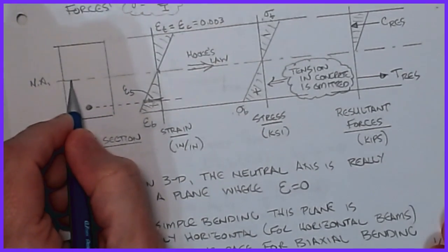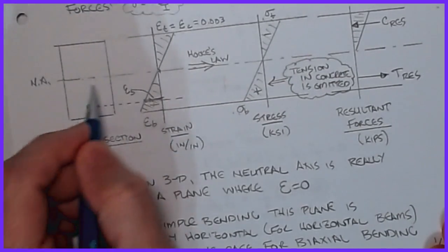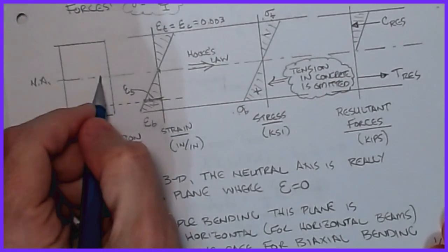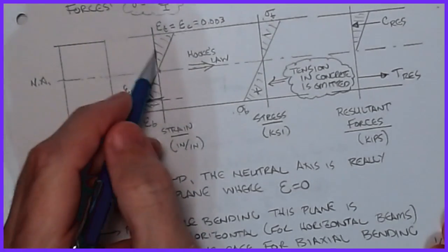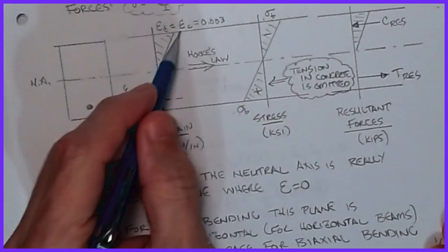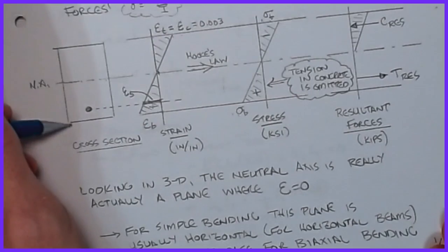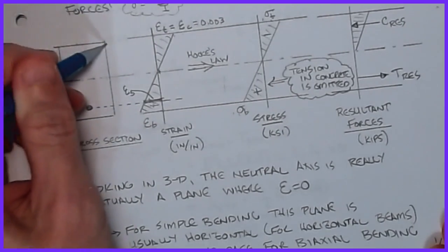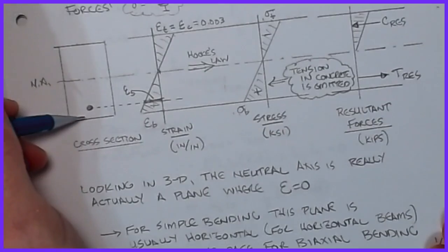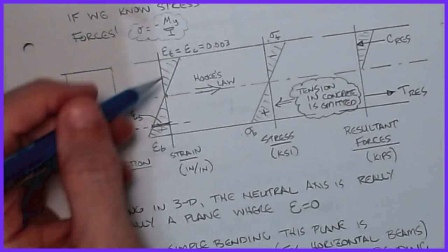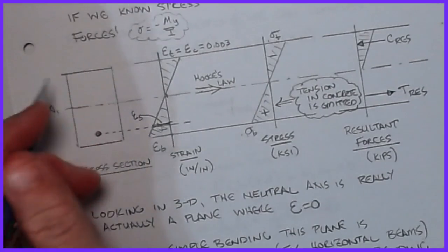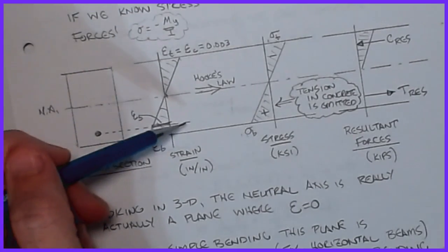It'll be 0 here, and it'll be 0 here, and so forth. So if you think about it, this diagram occurs at all locations along this beam. So I have the diagram here, and then I have it in the middle, and I have it at the end, and every situation in between. But because we have a constant width, we draw it two-dimensionally like that.